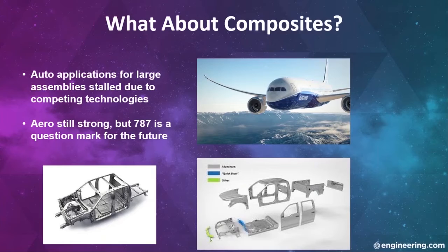Now, for those ferrous alloys, the industry is still talking about down gauging. But the real secret that's little discussed is that it's FEA and advanced simulation on the design side that are allowing thinner and thinner sheet and less of it while making it work with controlled deformability and crash survivability, as well as reasonable noise, vibration, and harshness levels and chassis stiffness.